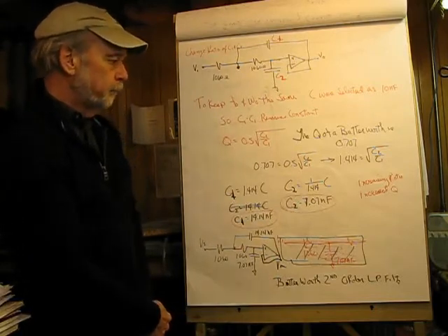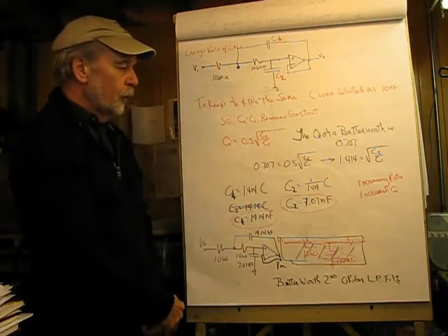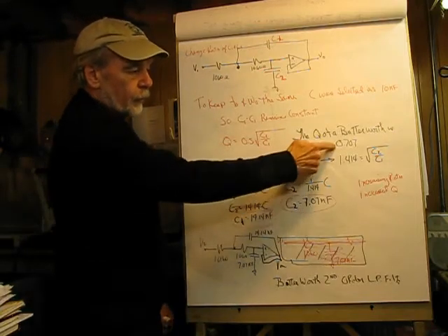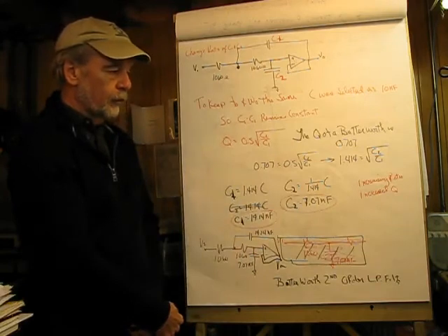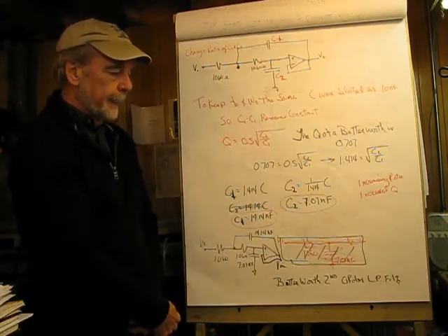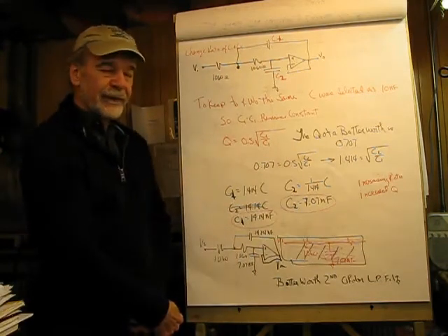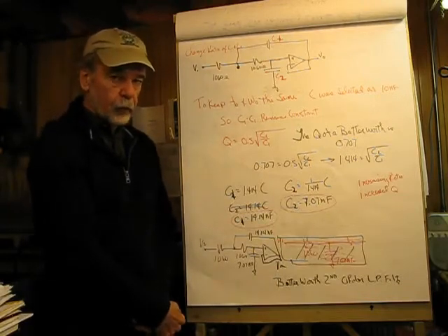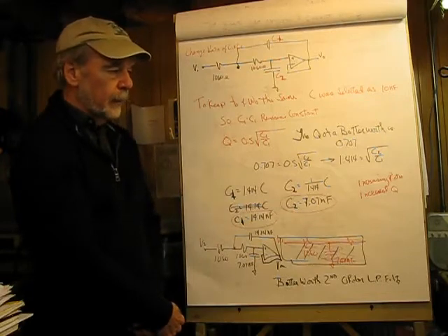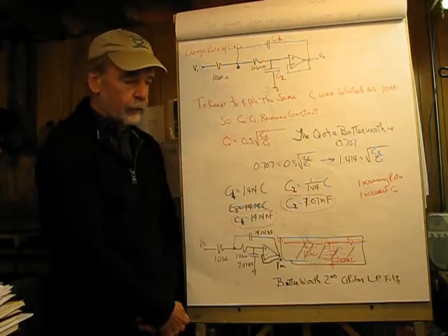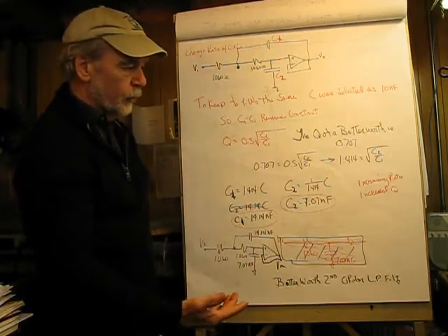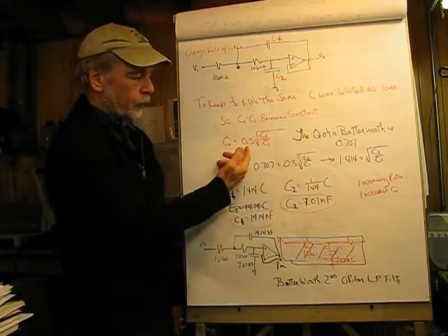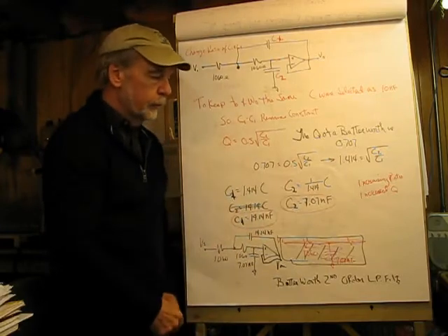So, C2 and C1, we're going to let these remain constant here, and as said before, this is the Q of a Butterworth at 0.707, industry standard. Now, let's see what we have to do to get the Q from 0.5, the critically damped frequency, up to that of 0.707. Now the equation which was developed before had this Q is equal to 0.5 times the square root of